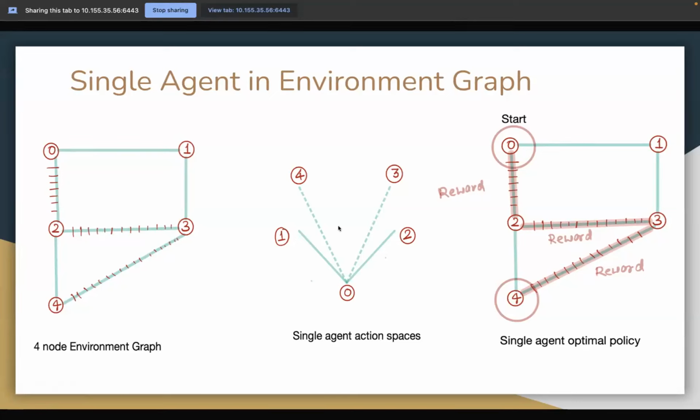So my approach of using this graph-based Q-learning was especially in the reward assignment. In the previous approach in our paper, team coordination using state-state graph, we tried to introduce this coordination behavior by reducing the cost when the agents coordinate. In this case, I have added a reward. There will be a reduced cost if the agents collaborate and traverse through this path. Doing that, the overall cost of traveling from the start to a goal position will be reduced, so agents will be more likely to take that path.